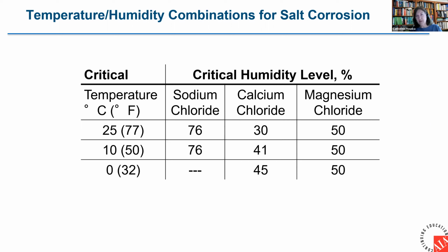For calcium and magnesium chloride, which are increasingly being used both as pre-treatments and in colder regions when the temperatures are going to go lower, all you have to do is be above freezing and at least 45% humidity, so very little moisture, relatively speaking, for it to start pulling moisture out of the air and creating a salt slurry on surfaces. And calcium and magnesium chloride are highly aggressive chlorides for deterioration of any material. So often de-icing salt applications are more corrosive than many that are in coastal areas, but you can, of course, have both.